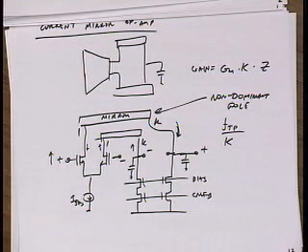Okay, yeah, Michael. It's again the one over f noise for the PMOS is lower. How about frequency response? How would you compare frequency response? Which do you think is faster? The NMOS? I mean, in order to get the same gm, I need to blow up the PMOS. Well, what really sets the bandwidth in these circuits? What's really setting your bandwidth? Is the dominant pole setting your bandwidth, or is it the non-dominant pole?